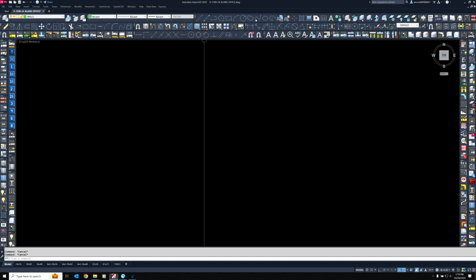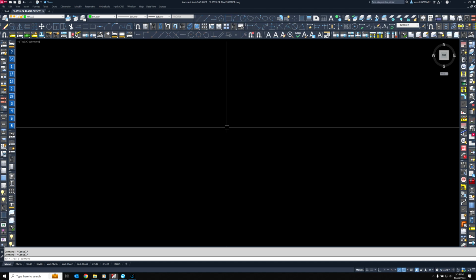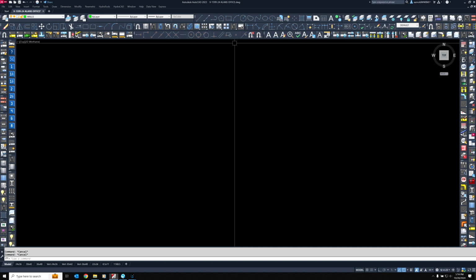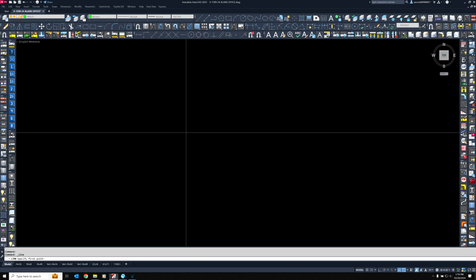If you span across, you'll see there are a few different ways you can draw and make shapes. If you hover, you'll begin to figure out what those are, and you can play with them inside the model space to get familiar. But we're going to draw a line, and we want this to start at absolute 0 in the drawing. You're talking XY coordinates and kind of a Z coordinate.